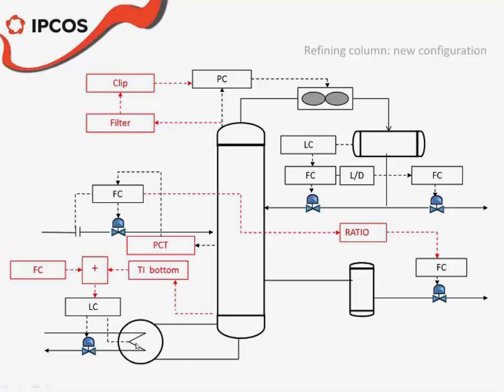This reboiler was just a steam reboiler. The level of that steam reboiler determines the heat surface, the heat transfer area. And if you have this level going up and down, then the duty is pretty much not controlled. You will just vary with it. So what we did here was we implemented feed-forward control to help this level controller to act on the condenser output by keeping an eye